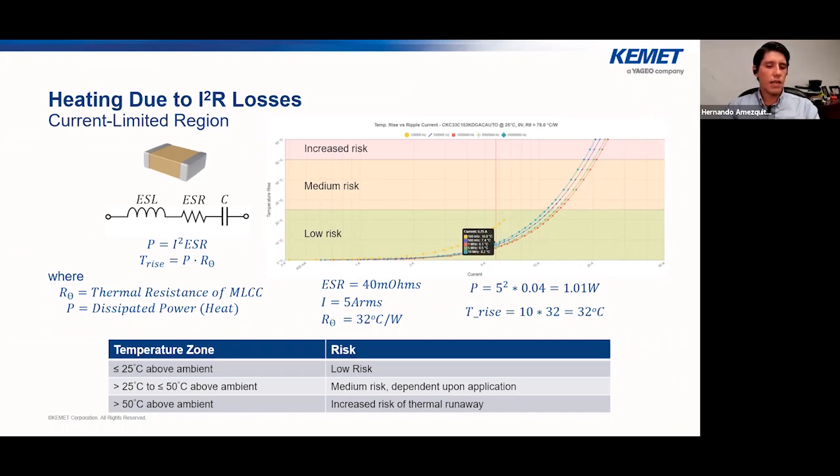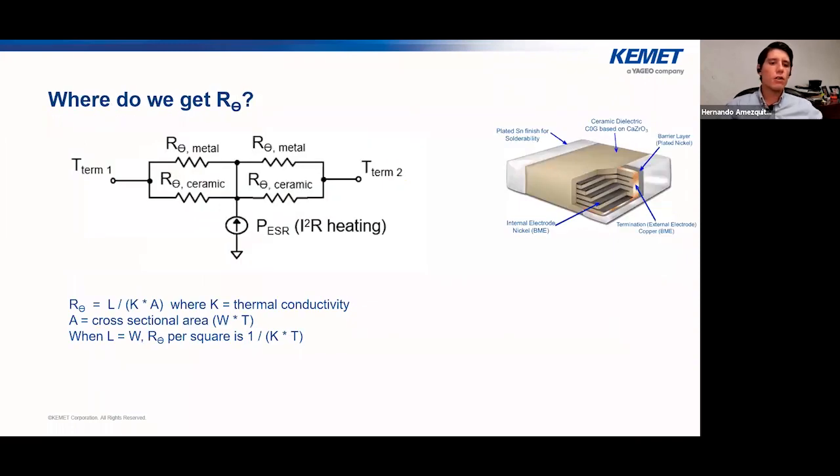And in the middle, you can see an example of how this can be calculated based on the ESR, the thermal resistance of the MLCC, and the current, and then you can calculate the temperature rise. Now, we are not going very deep into what thermal resistance is, but there are some important things to mention here.